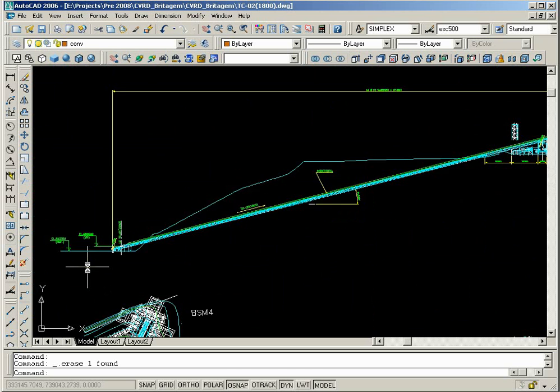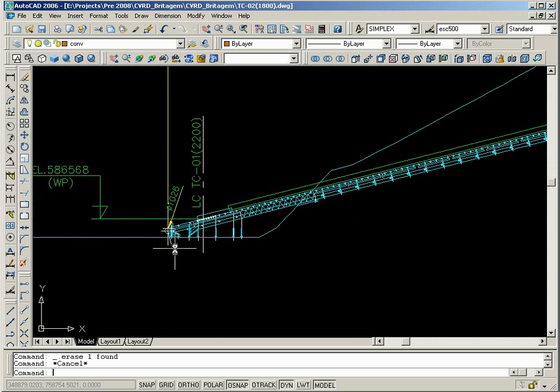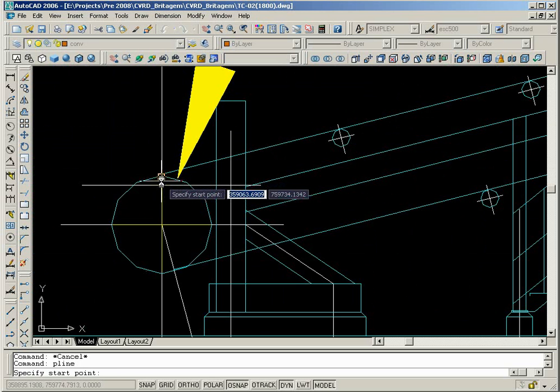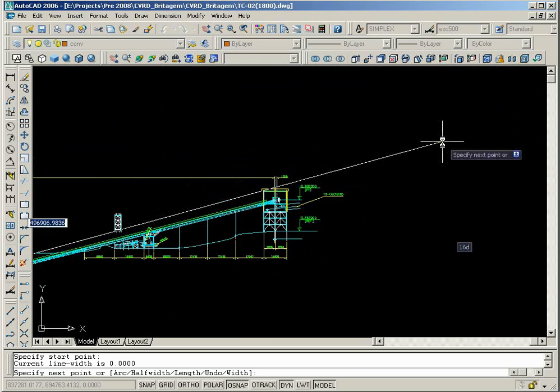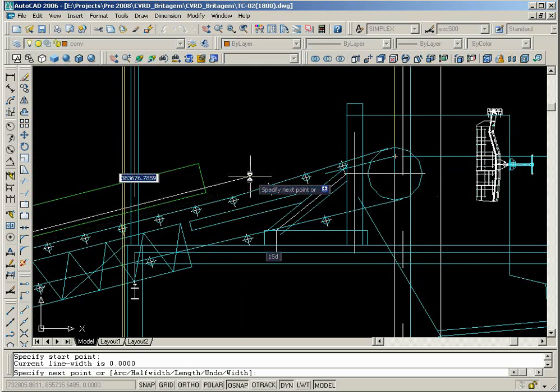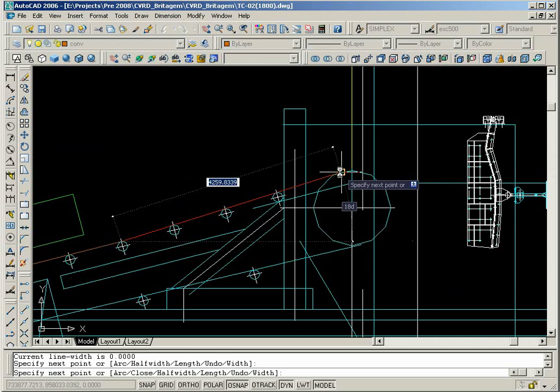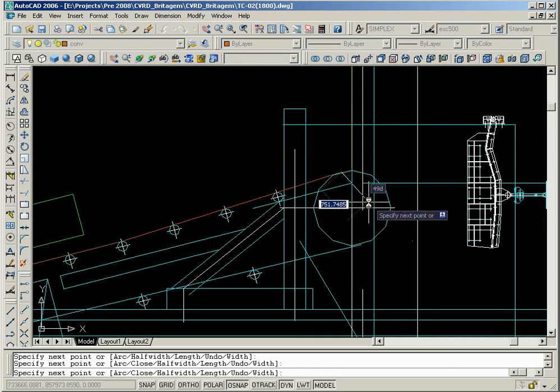So to start with, I could create a new layer or whatnot, but I'm actually just going to issue a P-line command, and we're going to start at the tail pulley here. On this particular conveyor, we actually have an elevated head pulley. So I'm going to click to there and create two elements on our carry side. Now at this point I could just snap across here and you'd see I have this short little 1.5 meter, 1.4 meter flight, and then continue on back.